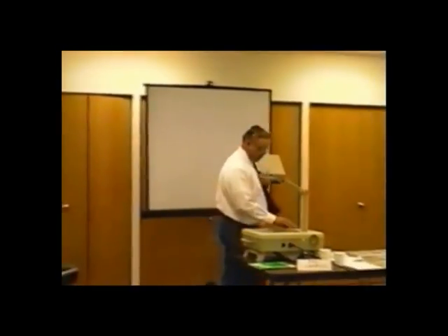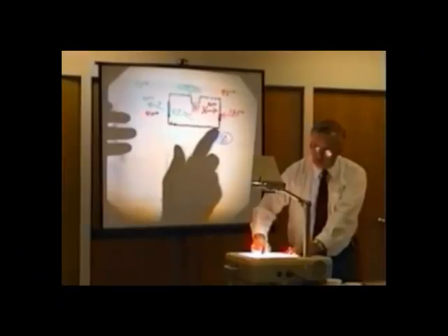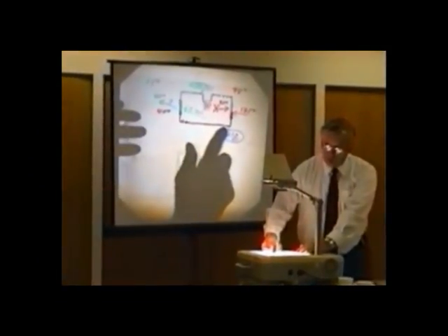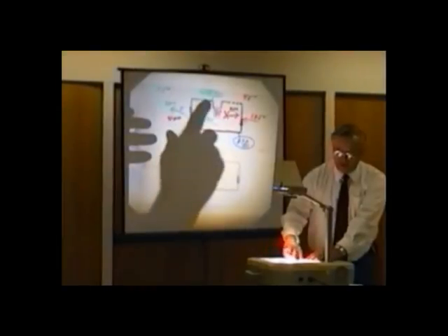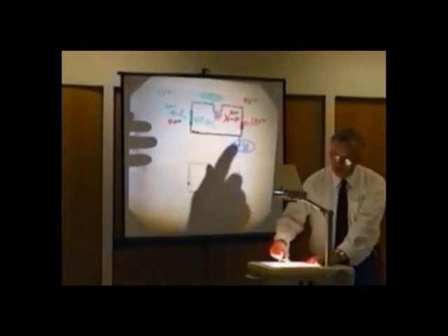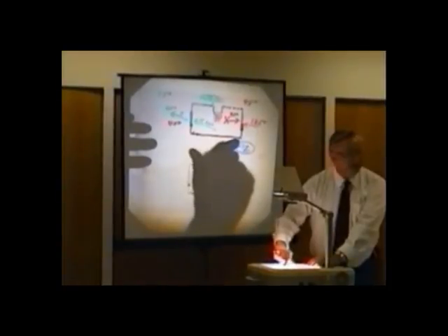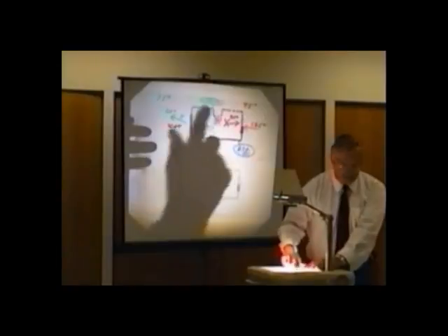We'll go back here to the transparency. The high side valve is close, the liquid line, where we want you to put the thermometer, is right by the high side valve, and the suction line temperature with the thermometer is right by the low side service valve. So the service valve is on the bottom of the condenser for the high side, and right before the compressor on the low side. Okay?